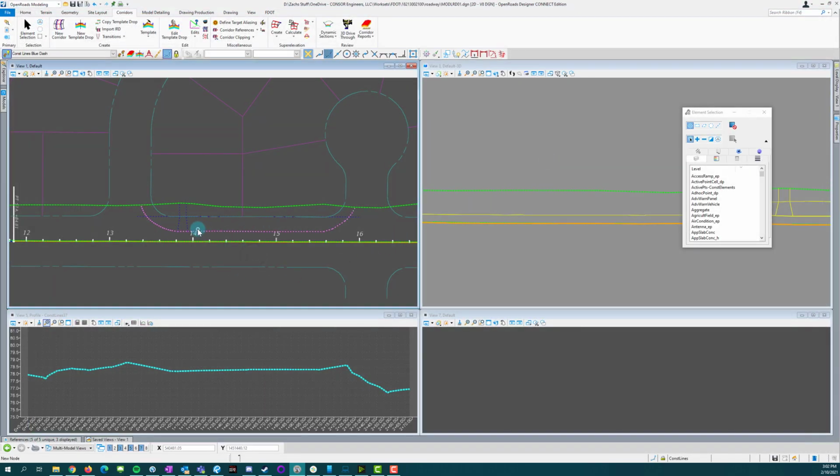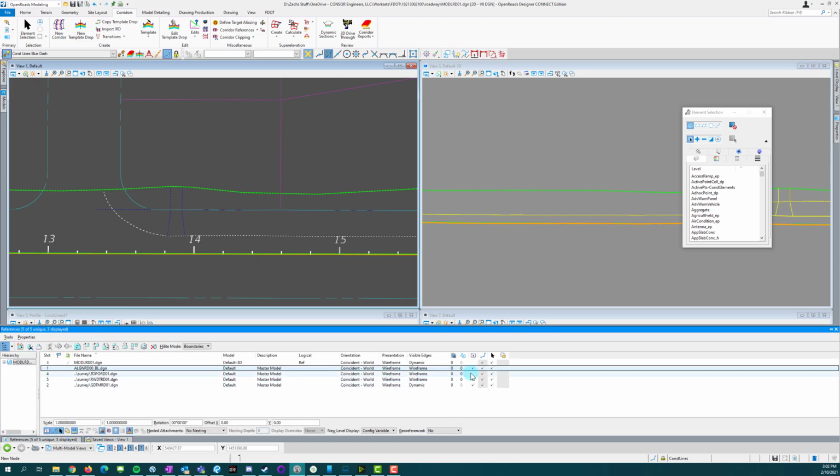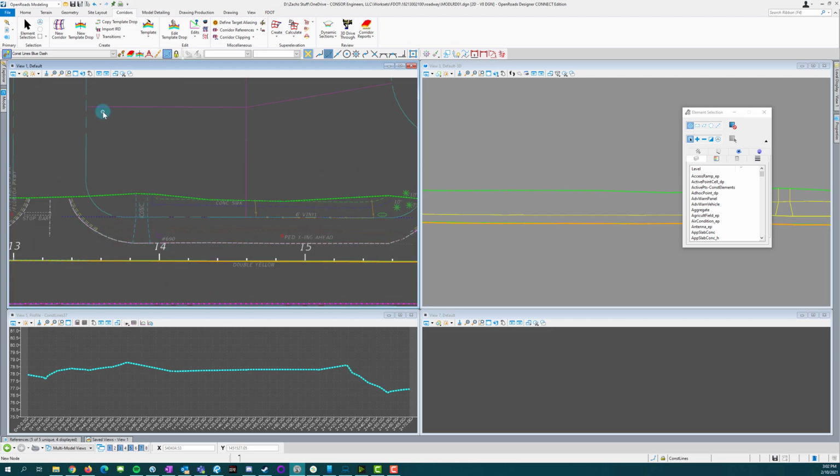And the first thing that we're going to need is a back of sidewalk alignment. So I want to look at this topo again. Looks like we got a fence. Okay, so there's a fence out here, but that's basically at the right-of-way line, so that's okay. I'm going to say typically, we have a 2 foot flat back there. You can reduce that to 1 or even 0 at times if you can still achieve that 1 on 4 or flatter. And that'll all depend on the client that you're working for and if you're still inside the clear zone. Several factors go into that, but those are some of the little tricks you can do to get as close to the right of way line as possible.